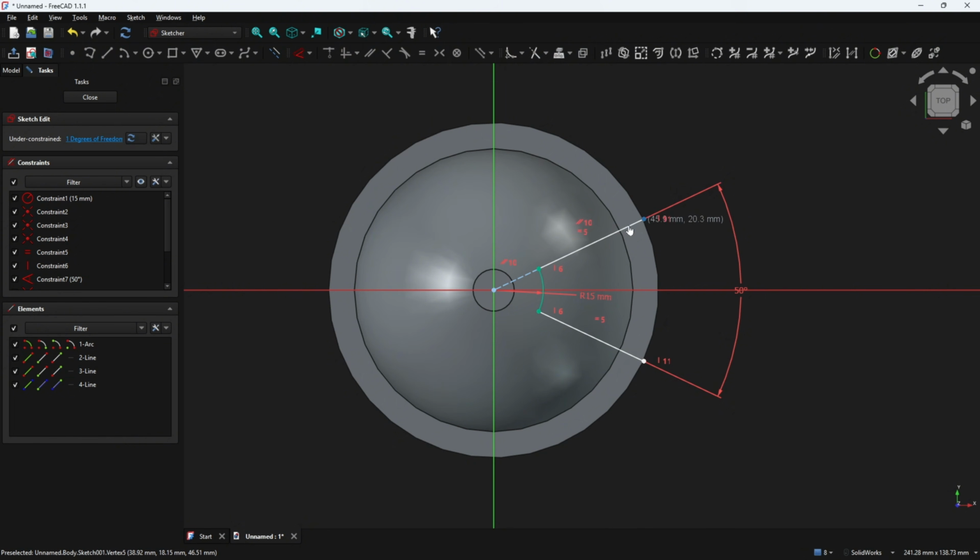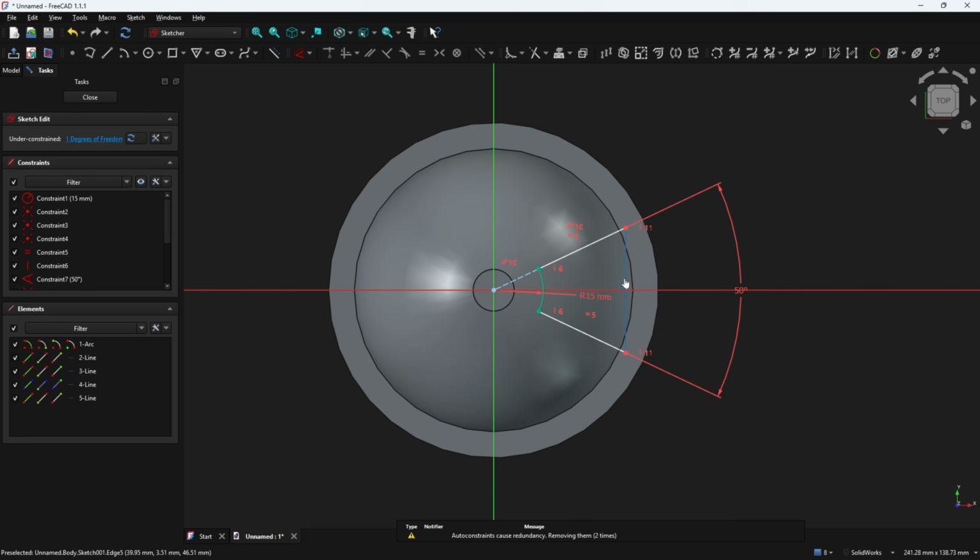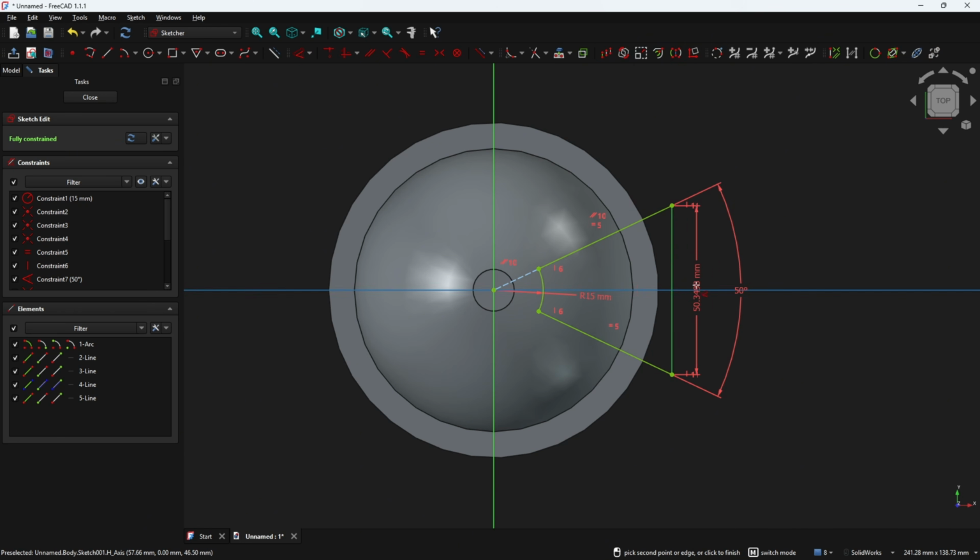Okay. And now remove the construction geometry here and select line, make a line between these 2 points and move this a little bit here and go to sketch dimension. The length of this line here can be 50 millimeters. It is just to define this profile, okay?